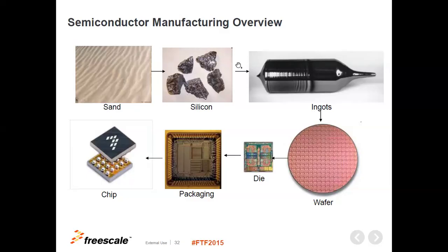When we heat it up again in a controlled way, we can create ingots, okay? And for example, we can cut the ingots transversally to obtain the so-called wafers, okay? What we are going to see at ST Microelectronics will be wafers of silicon that we can print, okay? These wafers are basically the substrate on which we can print all the things and so on and so forth.